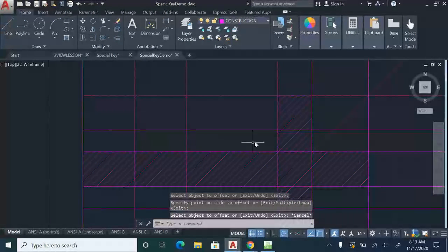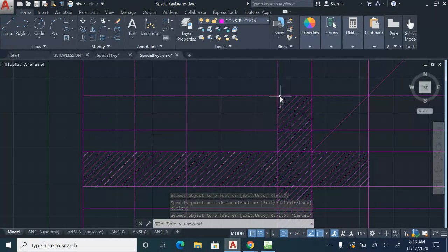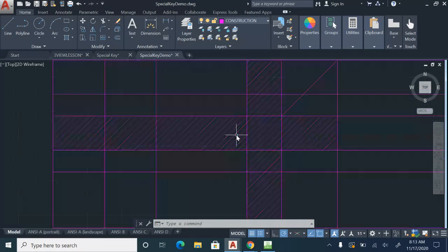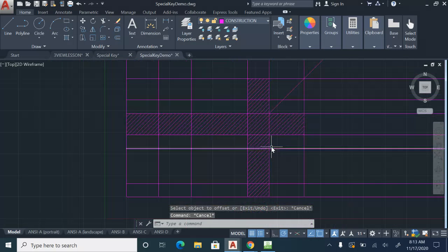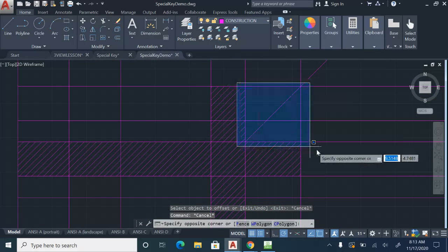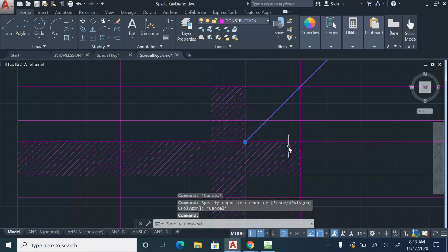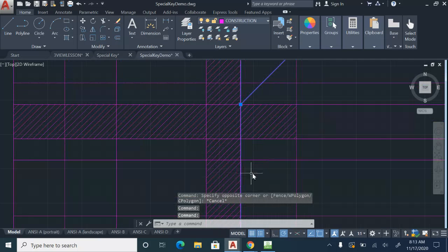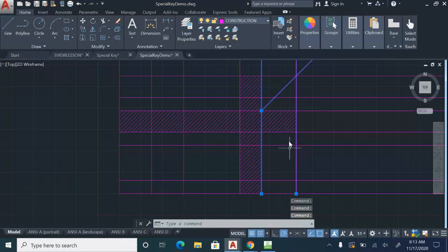Now, if you look closely, my top view is now finished. I just have to trace over some of this with a visible line. The last part of this is the right side view with the projection point, the 45-degree angle. I already have the left edge and the right edge of the right side view.